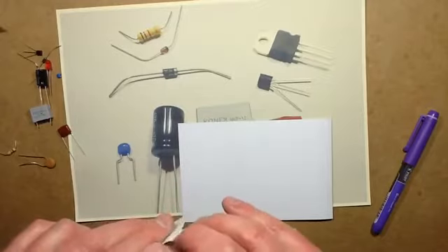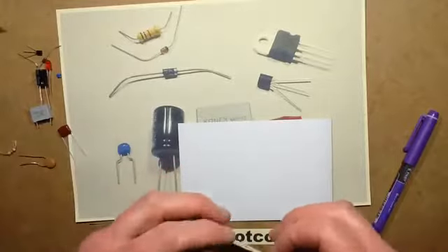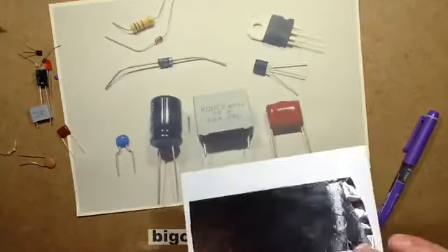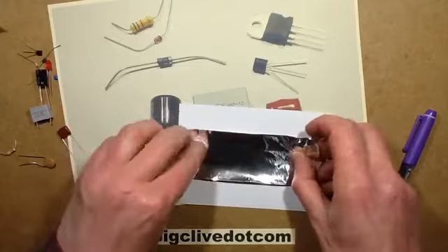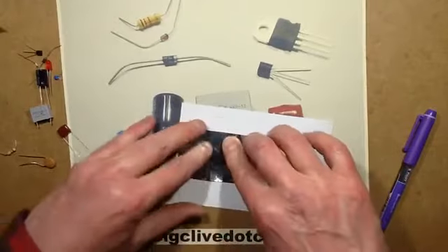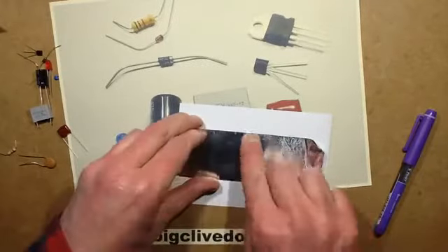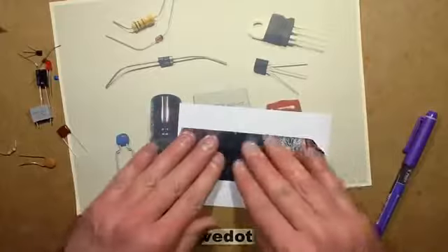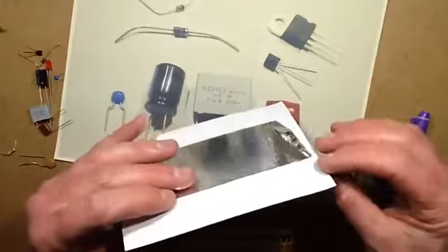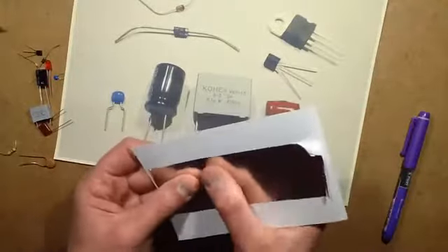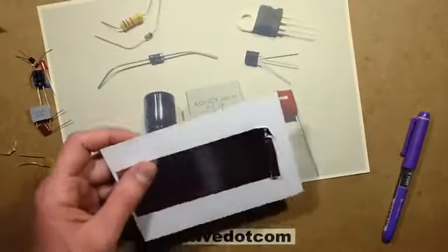And this is the physical construction that's used throughout all capacitors. They're all pretty much like this, but not using cardboard and aluminium foil. So let's get that pretty much as close to the other one's alignment as possible. And the 2 factors determining the capacitance here are the area of metallization that's in parallel with the other one, and how thick the insulator is in between. And you'd think, this card is very thin, so it's going to be a modestly high value of capacitance, but that's not true. This is not going to be a high value of capacitance at all.